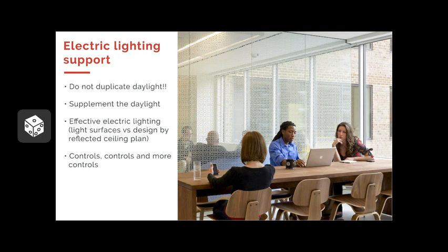Here is our beginning of electric light design. You always begin with daylight. Make sure that your daylight is beautifully designed and coming in with minimal glare. And then the electric lighting does not duplicate the daylighting, it supplements it.